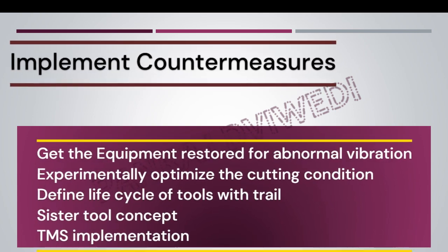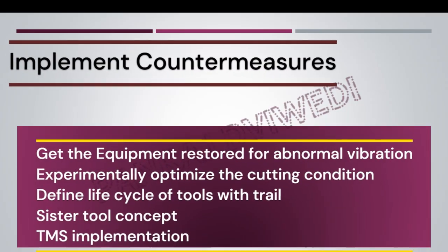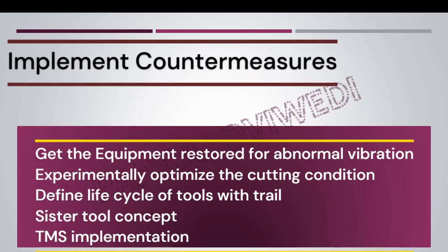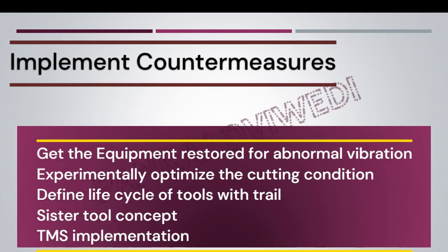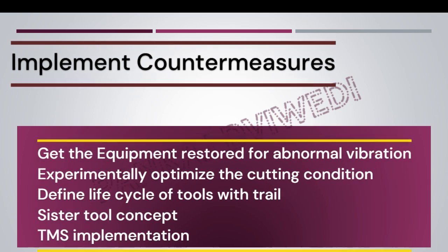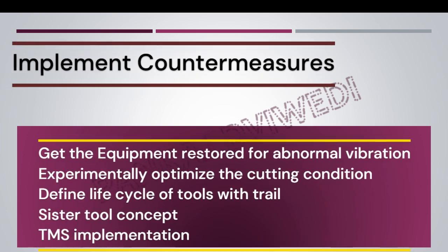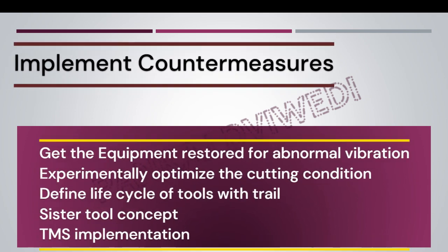Similarly, for electric current and effective power of the motor, please verify it with the motor capacities and the process requirement of cutting feed and speed. If they are matching, continue with this. If it is not matching, it means that the motor is not enough to meet all those requirements, and you should think of shifting the operation to some other machine which meets the power requirements.